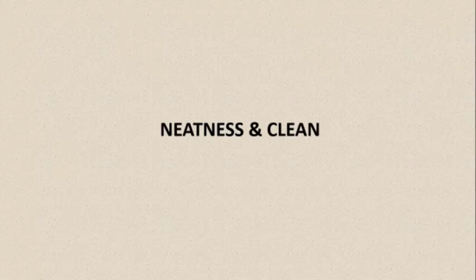That is why it's important to make reassessing your ISO classification part of your clean room procedure when you take on a new project or unit as your laboratory changes. That's because every industry and every application has a different set of cleanliness requirements. Clean room classification addresses the level of cleanliness in the air according to particle size and concentration.